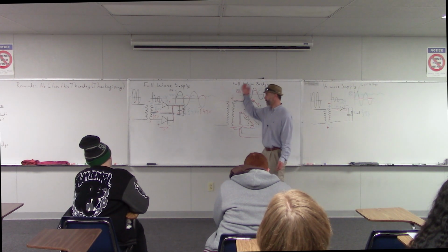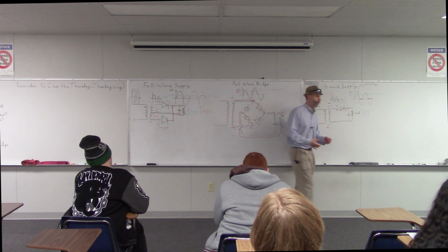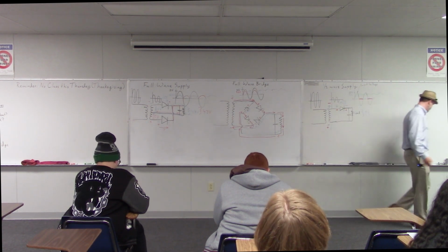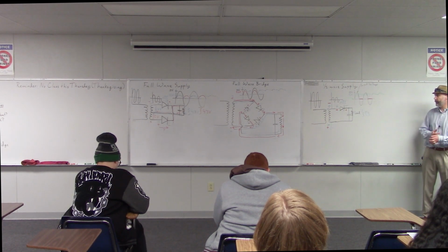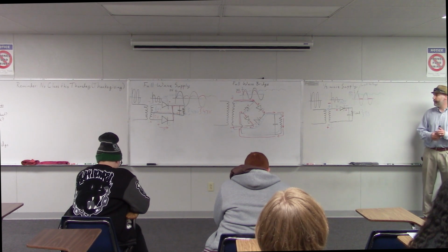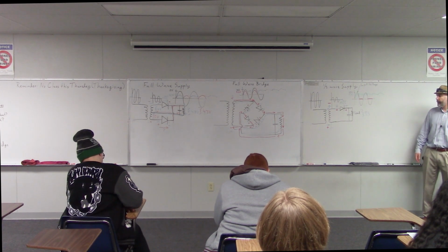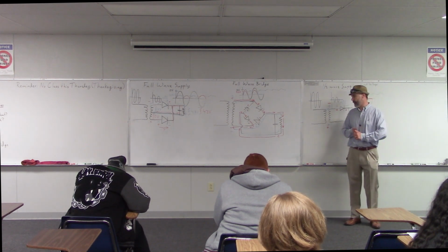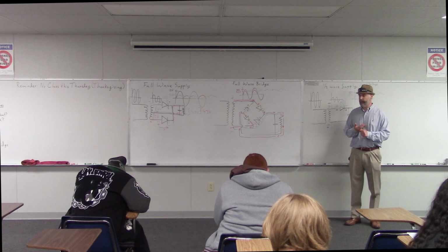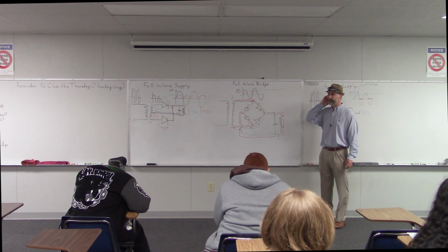Not many people use a full wave supply because of that center tap. So if you are building something cheap and you don't really need a smooth power supply or a lot of efficiency, then you can get away with a half wave supply, and people do that. If you're building something that needs a little more precision and efficiency, people typically use a full wave bridge supply.